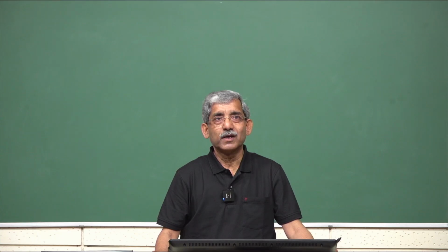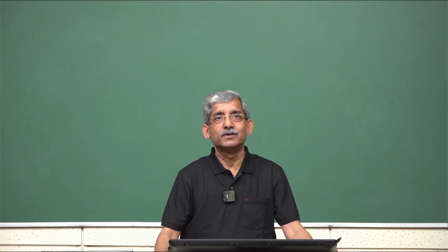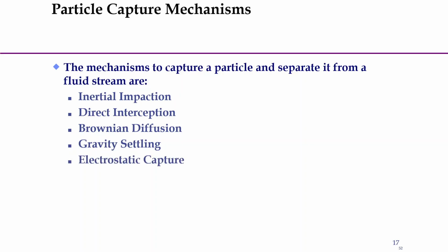Hello everyone. So, we are discussing the particle capture mechanism during air filtration. These are inertial impaction, direct interception, Brownian diffusion, gravity settling and electrostatic charge. Electrostatic capture with the help of electrostatic charge helps in capturing the very smaller particles, that we will discuss in detail.